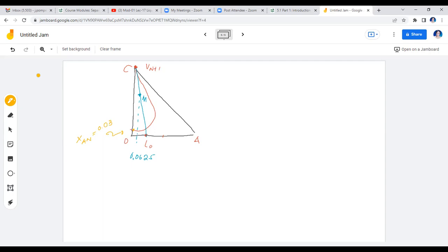You project up until you are on the lower part of the phase envelope. If you recall our discussion regarding the location of the raffinate points on the phase envelope, it's on the lower part. The extract points on the phase envelope are on the upper part. So that is why, after you have determined the 0.03 or the 3% here on the horizontal axis, you go up and project that particular composition on the phase envelope.